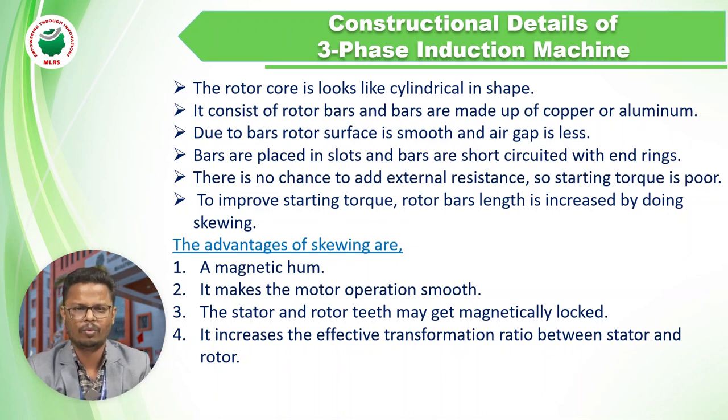Wherever we require constant speed rotation applications, that is, even though the load increases, the speed should not change over a wide range, there we can use these squirrel cage induction motors. Mostly 90% of applications use squirrel cage induction motors compared to slip ring induction motors.